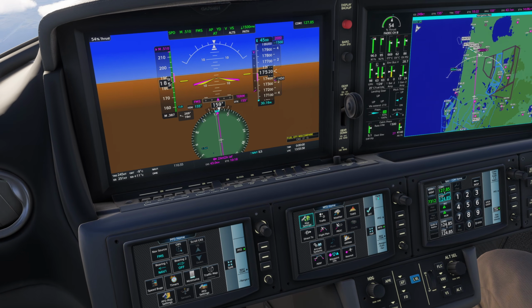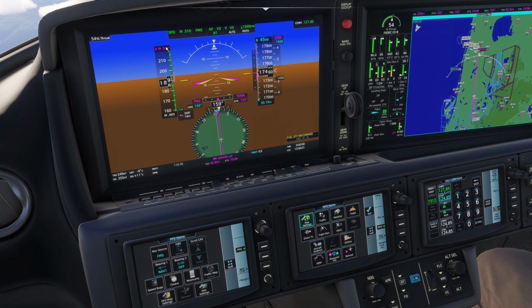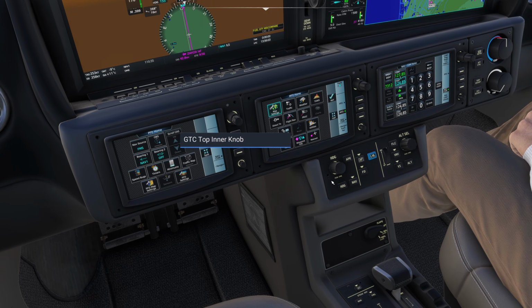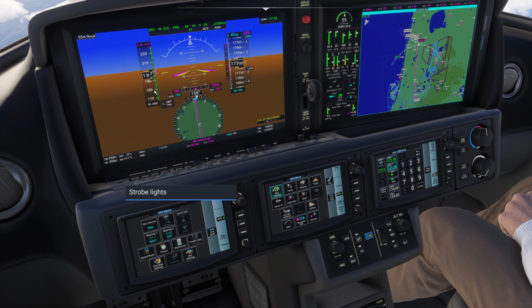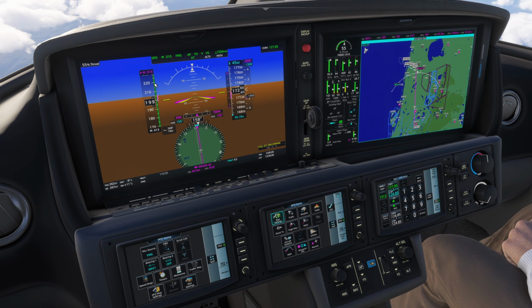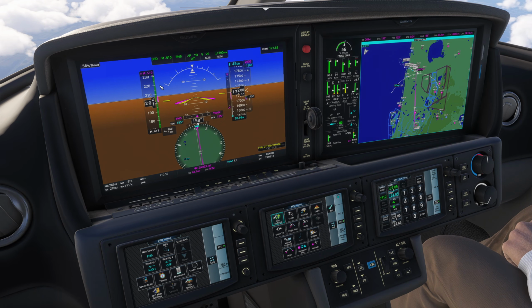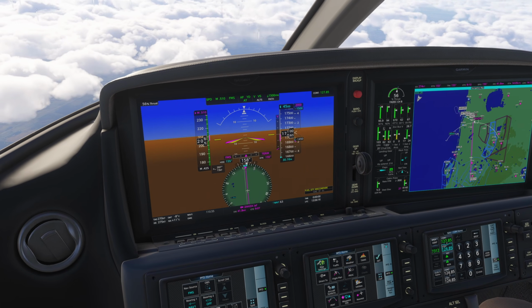We are going to gain a lot of speed. So what we'd want to do, as you can see, our speed has changed from airspeed to Mach. We'd want to reduce that speed, or we can see if the plane is going to not go above our 250 knot speed, which it shouldn't. So we'll leave it for now and see how the FMS is going to handle it.